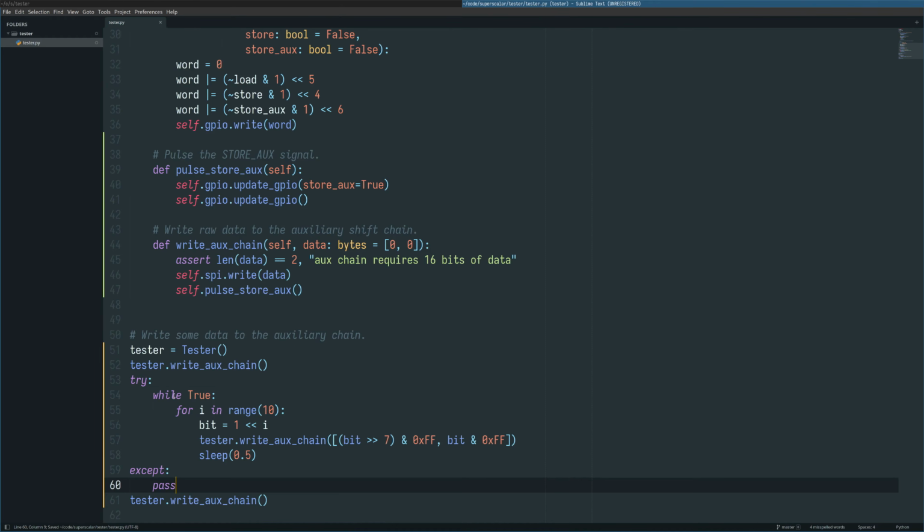And so what that does is, when we're stuck in this loop and we're basically animating the LEDs, if I hit Control C on the keyboard to cancel out of the Python script, instead of just aborting, this is going to throw an exception, and we can basically gracefully turn off all the LEDs that are visible. So we have a graceful shutdown of whatever we're doing.